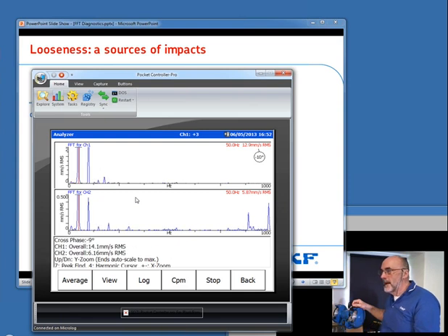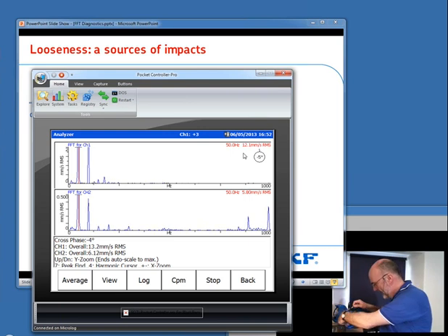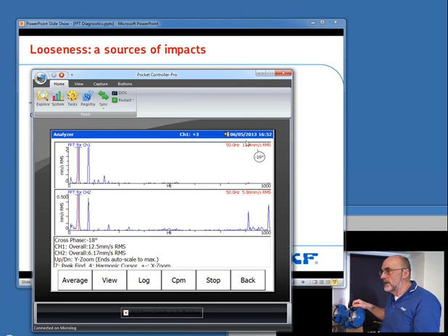It's dropped away now. And the phase reading has now gone back to being stable. Oops, sorry, it's still got a little bit of looseness. There we go, got rid of it. So the baseline has dropped back to where it was, and the phase reading has gone back to being stable. One last try. Loosen the tool post. The phase reading should become unstable. Yes, it has. It's gone from 3 to 19, and we're starting to get this background energy across the base of the spectrum.